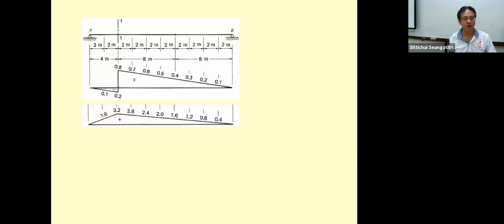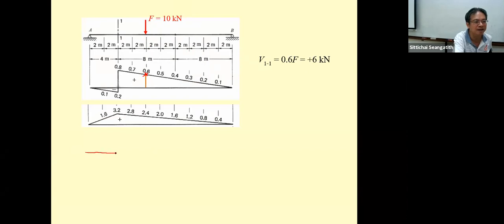And then coming to shear, this one is what? The force times the coordinate. So for the shear at section 1, the shear V1 will be equal to 10 times 0.6. Under the force there, if you remember, we got the reaction A sub y of 6 kilonewton.